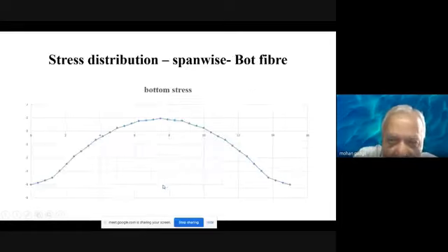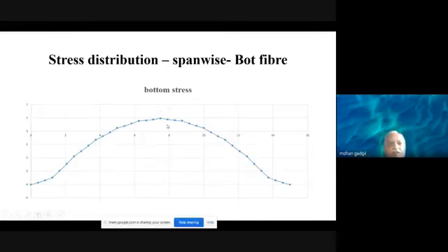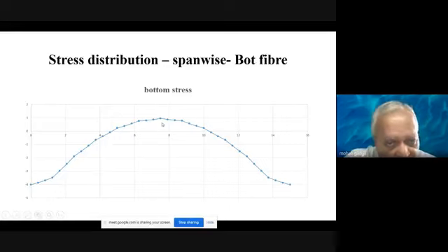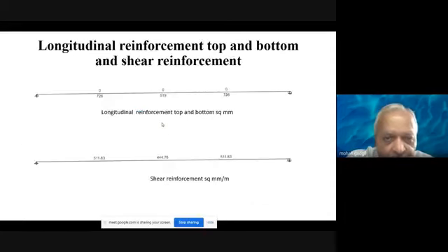Same thing happens for tensile stresses. Now tensile stress is generally limited in such cases to about 10% of fck, that is 0.1 fck. So you will be able to go up to 3.5 Newton per mm square, while actual stress is 1. So you can say that your beam has got satisfactory parameters, and this beam can be designed with prestressed cables, 12 cables you will have to use, and so on and so forth. So this is the way we consider the design of the beam.